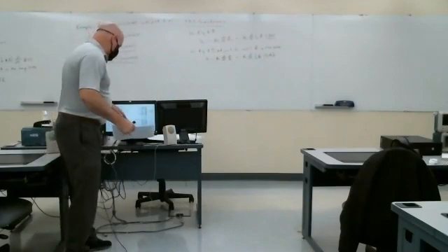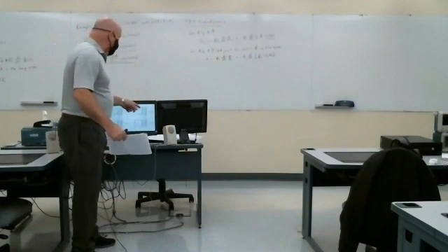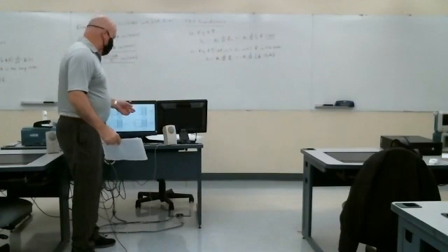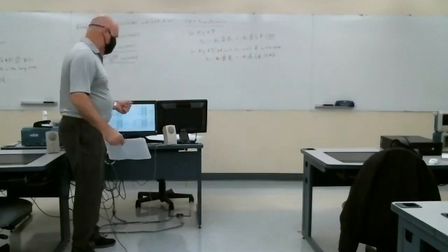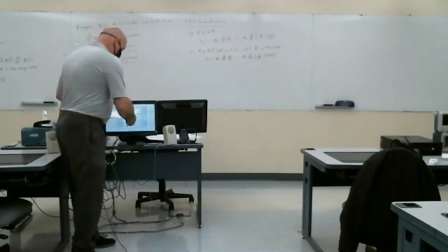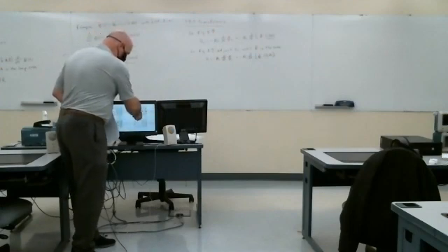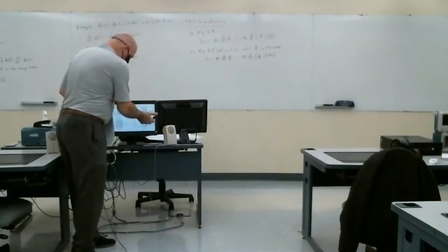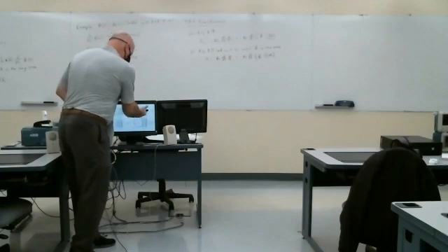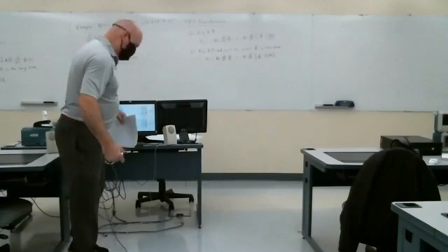Now when I switch the cases, again, the surface area direction here depends on my assumed polarity for V1. So V1, I've assumed it's positive at the top. So current is flowing from the negative terminal in the loops and out the positive terminal. So with my thumb in the direction of current, I curl my fingers up inside the coil. In that case, that normal is positive Z directed.